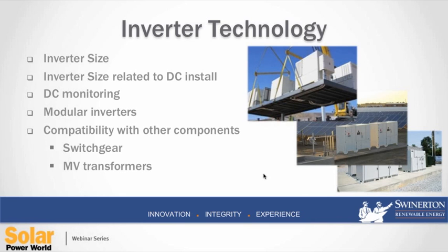And then for many new inverters that are coming, we're seeing a trend to go into a modular approach where you have inverters being built with multiple engine components, and they're differentiating themselves by taking a modular approach where one module may go out, but you have a 1.5 megawatt inverter, and maybe you lose a 250 kW chunk of that inverter and not the entire inverter. So we're seeing that being a big push, especially in the larger scale projects.